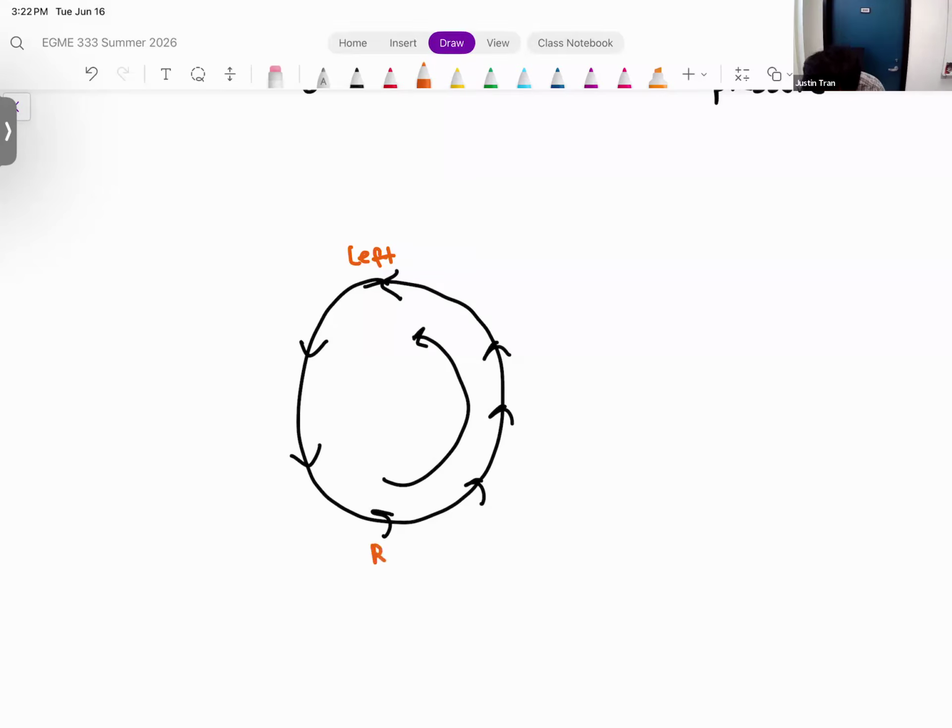And on the bottom, our spin is going to the right? Just because that's how spin works. Okay? And when you combine that with the uniform flow, remember, part of flow over a cylinder is that we have this uniform flow that's passing over the top. Okay. And the uniform flow is going from left to right. All right, and so what tends to happen there is that for the top of the cylinder, where our spin is going to the left, that's going to slow down the flow on the top.